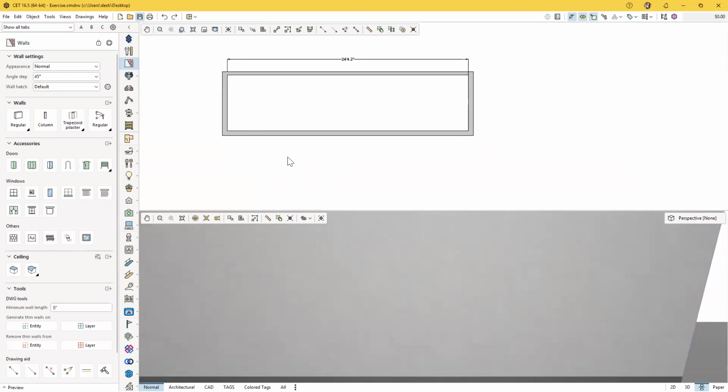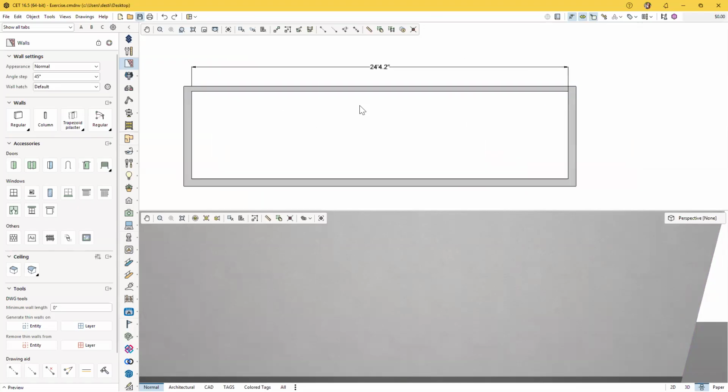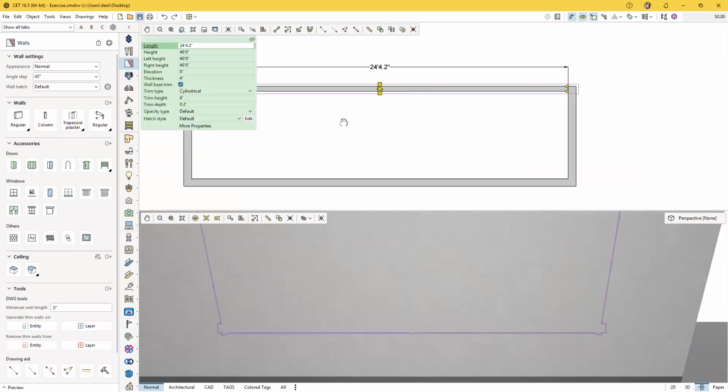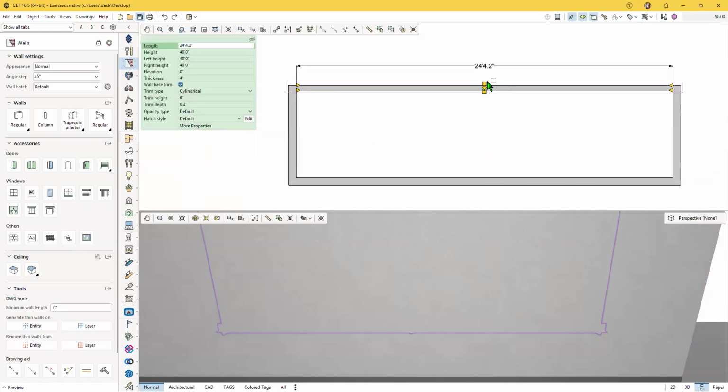All right. Same kind of thing when we're talking about space. If we've already got a defined size here, if you go to stretch your wall size, your wall thickness, again, this is where you want to actually use those stretch nodes instead of selecting a value here in the quick properties. Because let's say that I need a very specific interior size, but your wall needs to be a little bit thicker.